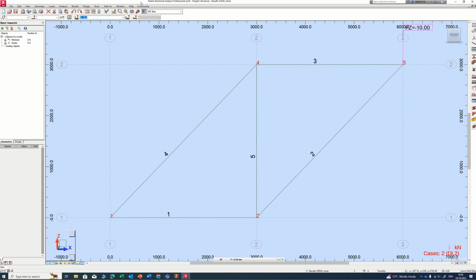And then what we need to do is that the second one, we need to go to the combination, because we want this loading. I want to see the third case is a combination of these two loadings, so we cannot use this separate load case function anymore. We need to go to here, go to the loads, and then we need to manually create that combination by clicking on this one. And then that will be the load case combination 3. So it's a combination 1, but it's load case 3.